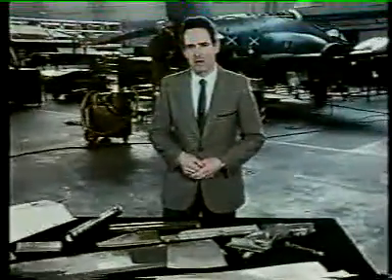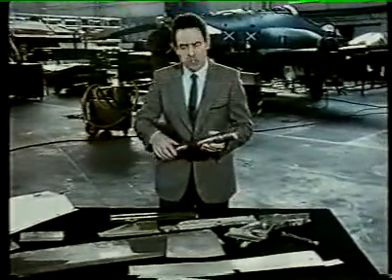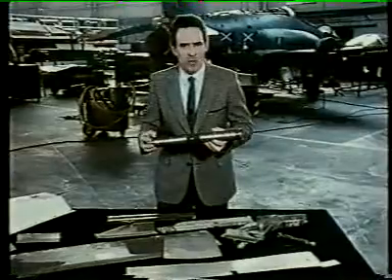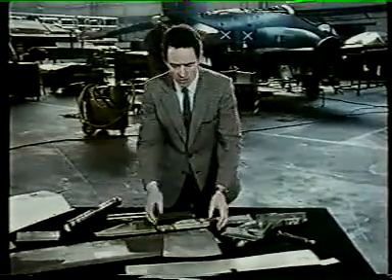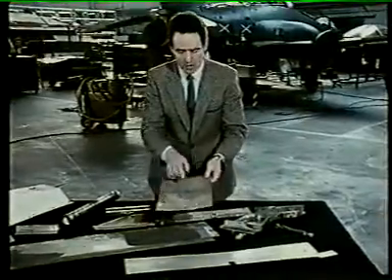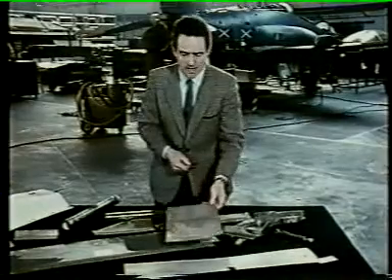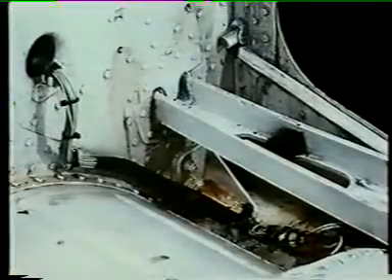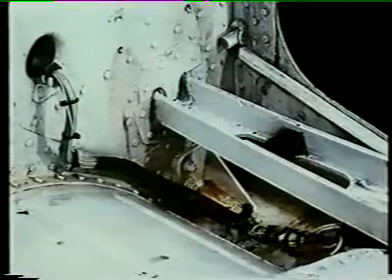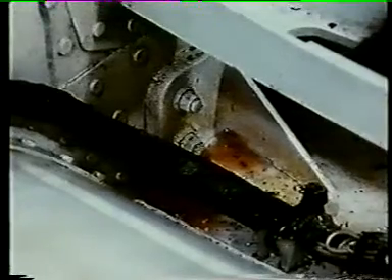So what form does corrosion take in practice in RAF aircraft? What should we be looking out for? One of the commonest forms is surface corrosion, a general etching away of any exposed areas of bare metal. Pitting corrosion is more localized and occurs particularly where strongly corrosive agents are found, places such as battery compartments, toilet and galley areas. Any crevices that trap liquid are also very prone to corrosion, as the lower oxygen content of the trapped water gives rise to an increasingly acidic galvanic cell.